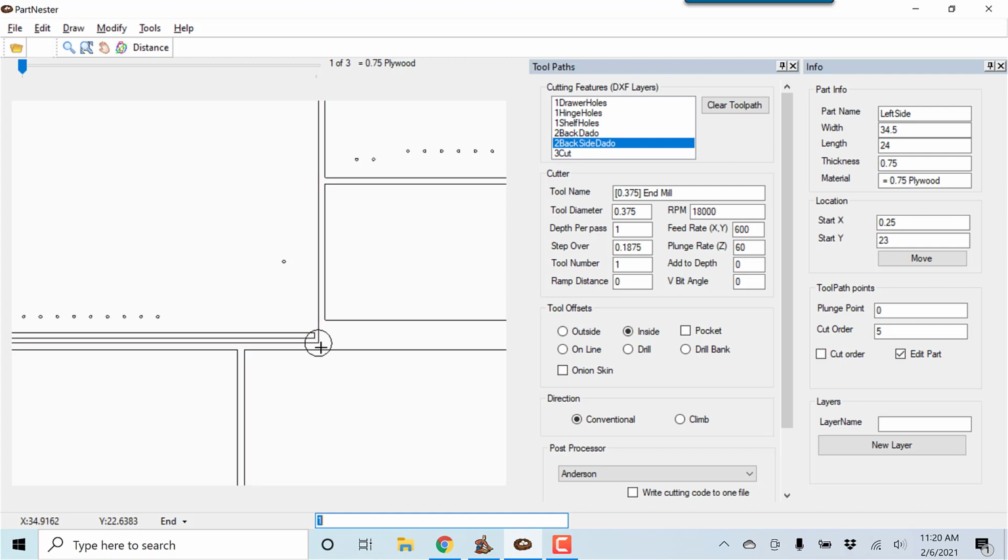But we want to have that part 2 inches down in the X direction and maybe 6 inches up or 4 inches up in the Y. We're going to do that with a 2-step process under Modify, selecting Move. It's asking what objects do we want to have moved. Select this. Now it's asking for the base point. So the base point really doesn't matter. I'm just going to select there, and you see that it is moving.